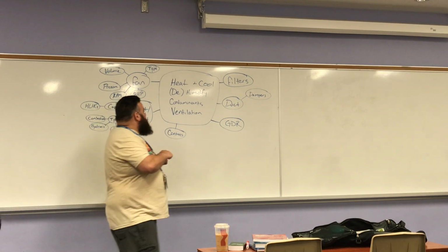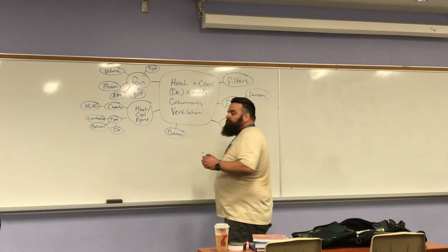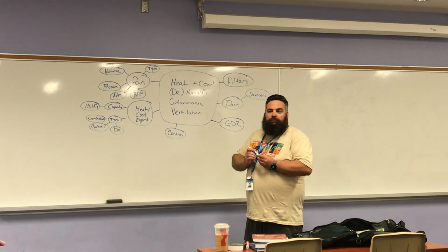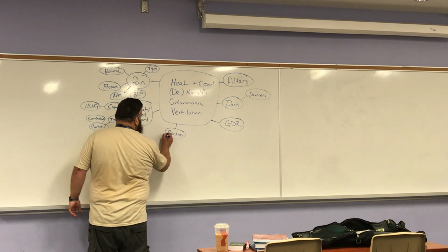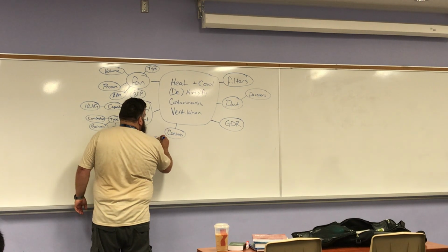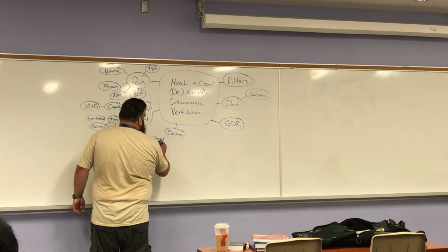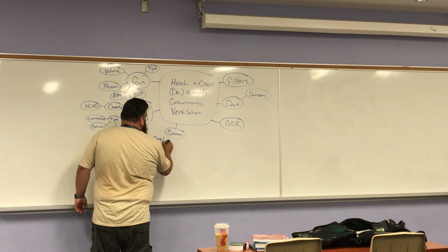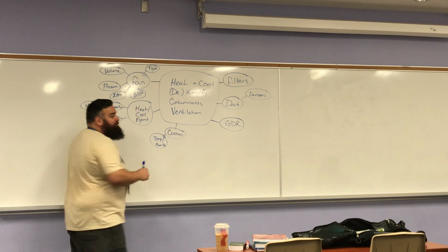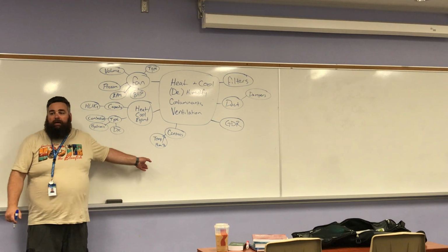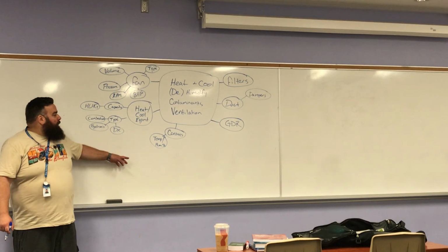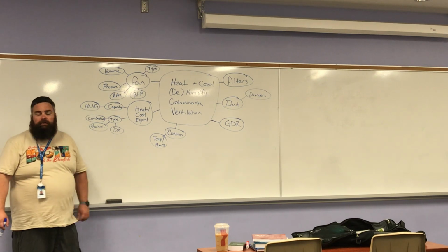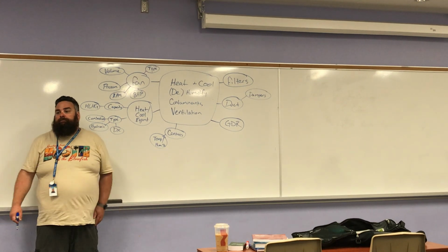What about controls? Humidity. So you're thinking humidistat. Yeah. So let's say temp humidity. Temperature control, like a T-stat. So I put here humidity percent, but we don't have to do that by relative humidity, we can do it by dew point as well, or wet bulb temperature, but it's just easier writing humidity. What else?